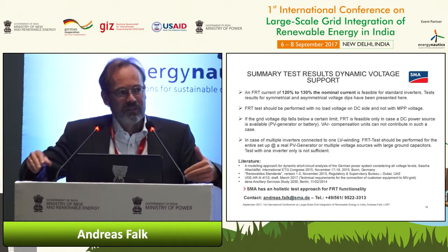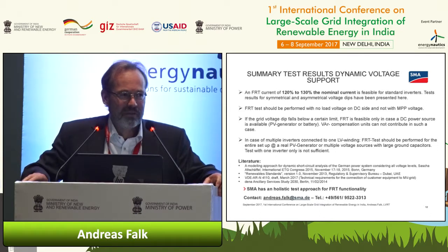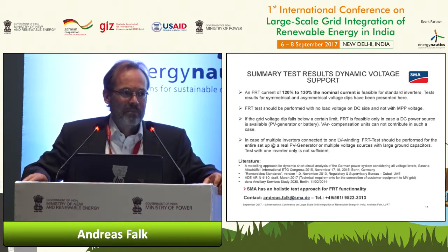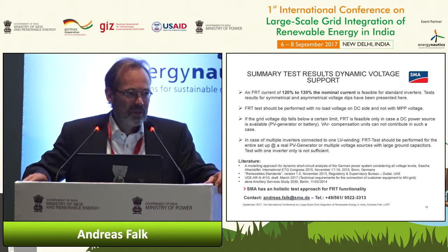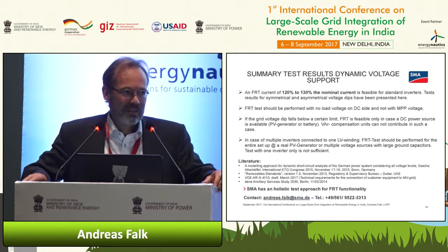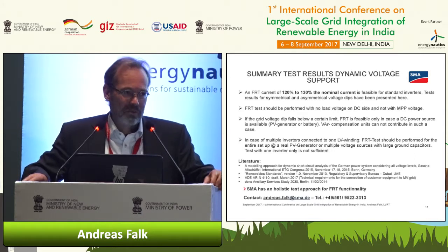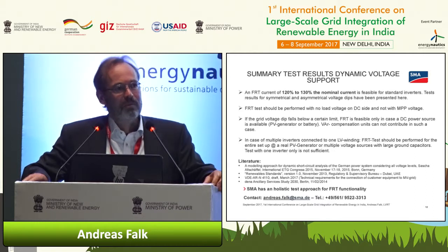When you have a galvanic coupled system, especially with the PV generator, because you have those large ground capacitors, then you have to test under conditions rebuilding the system, or at minimum in a type test.